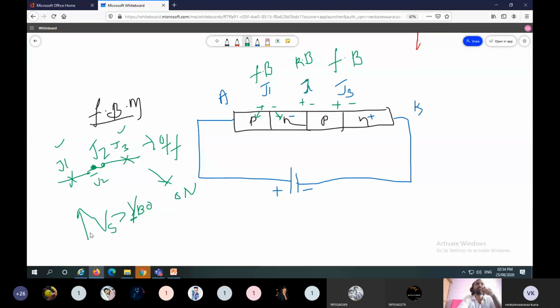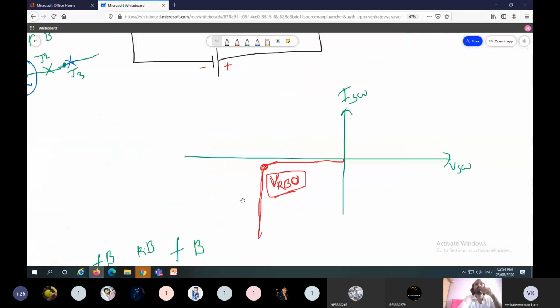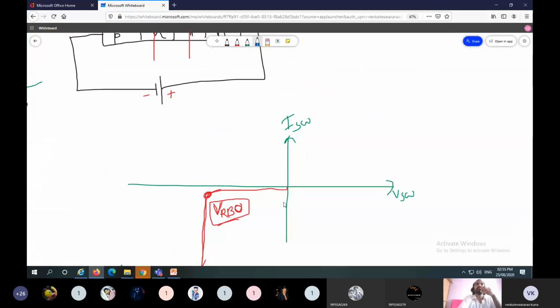So this happens only when the supply voltage Vs increases beyond VBO, the forward breakover voltage, and the device turns on. This mode is forward conduction mode. This one is the supply voltage and current flowing. There is also some amount of current that flows in forward blocking mode. This is a small amount of current.